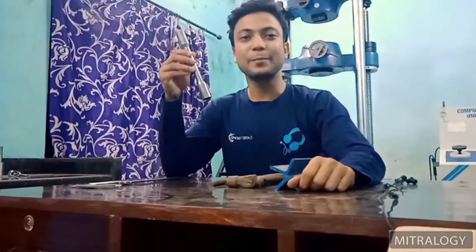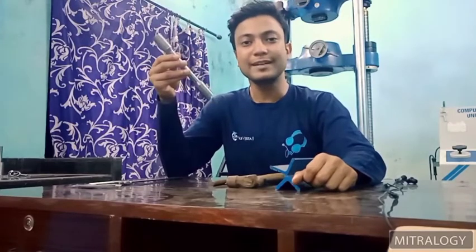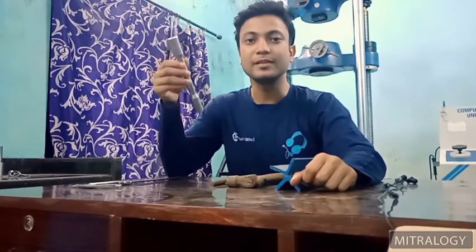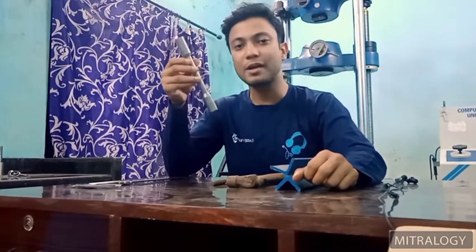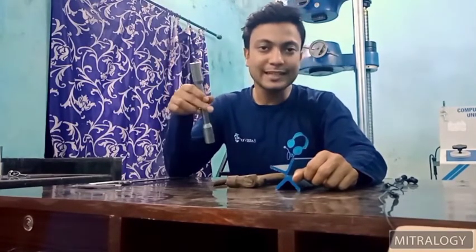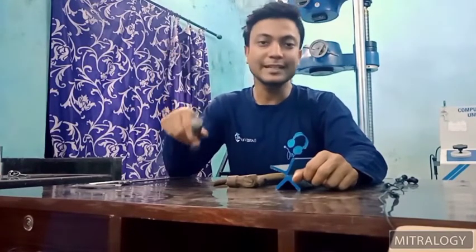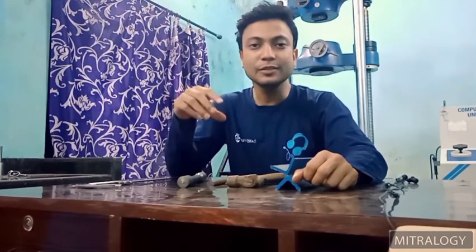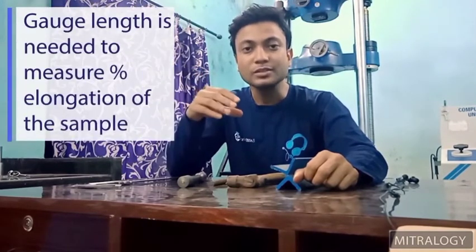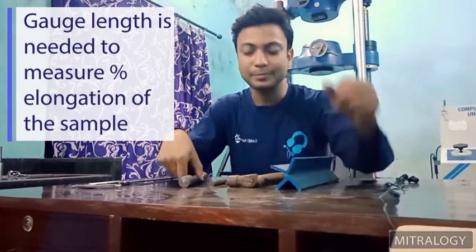So this is the sample for the tensile test. We can take different types of material and different types of sample, but generally we use a flat sample or a round sample. For today's tensile test, we use a round solid sample. Before starting the test, we have to measure the gauge length. Basically, we measure the gauge length to determine the percentage elongation of the material.